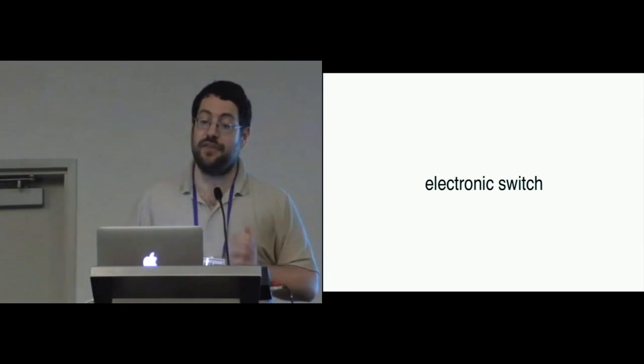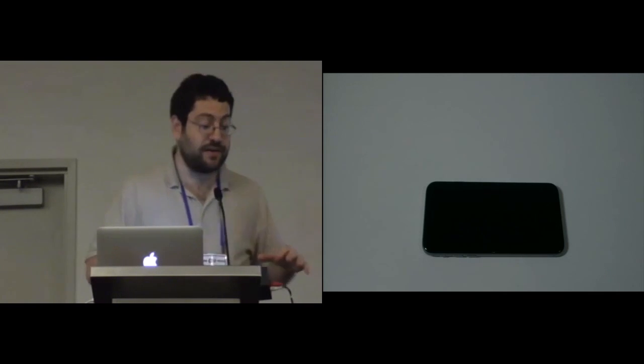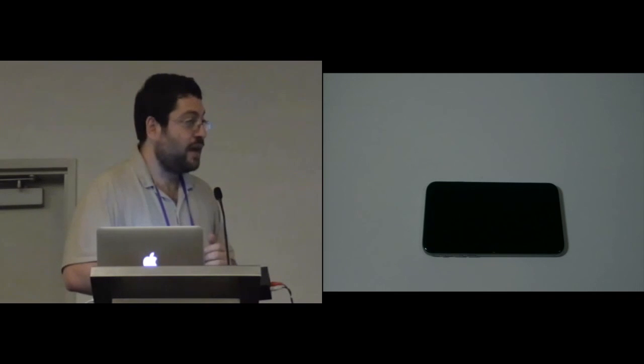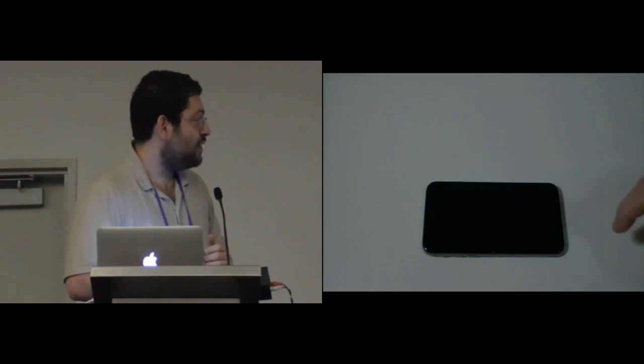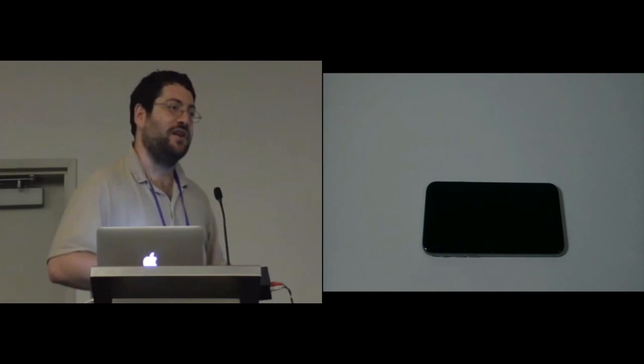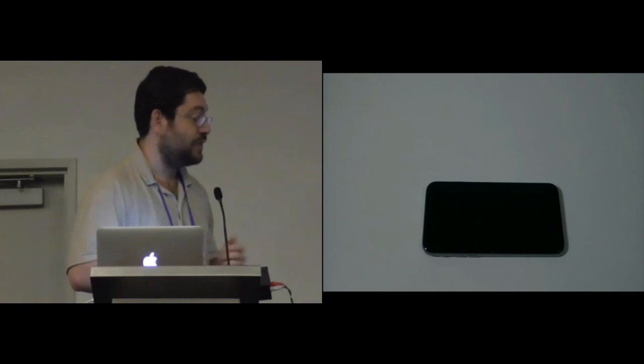The key to doing that is to think about how a capacitive touchscreen works. So there's a charge that's projected onto the surface of this phone. Electrons are sitting there, essentially. And when you touch it, some of those electrons are going to move into you because you're filled with water and have surface area, and that's going to change the capacitance on the top of the screen. The sensor then says, okay, here's a touch.